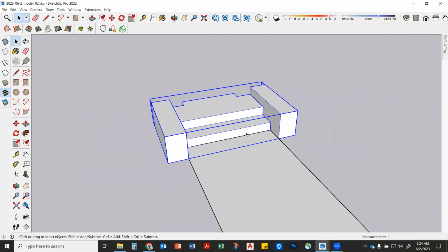Oh, that I haven't made yet, but look for the ones that have the same number of risers, yeah? Now, if it doesn't have the same number of risers, you can still start with this component. But what will you do to change it? Remember that process? Yeah, right click, make unique, right? Because a lot of these on the other side have like 2 more steps because they're coming down a little more grade. So then you just make it unique and then see how many of those you can just copy and paste. Cool?